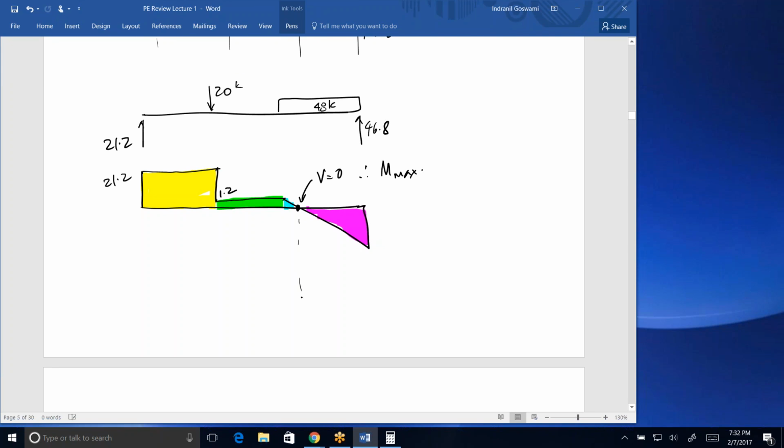So that means our bending moment diagram will look kind of like this. Over that last section, it'll be a parabola with a maximum here. I'm exaggerating because that's so tiny, it's probably not enough to make that much of a change. But anyway, it's going to be a parabolic section that looks like that. Maximum will correspond to that zero crossing point. And then it's rising slowly here and rapidly here. I didn't draw it to scale, but this rises quickly and then rather flat, and then the parabola, right?